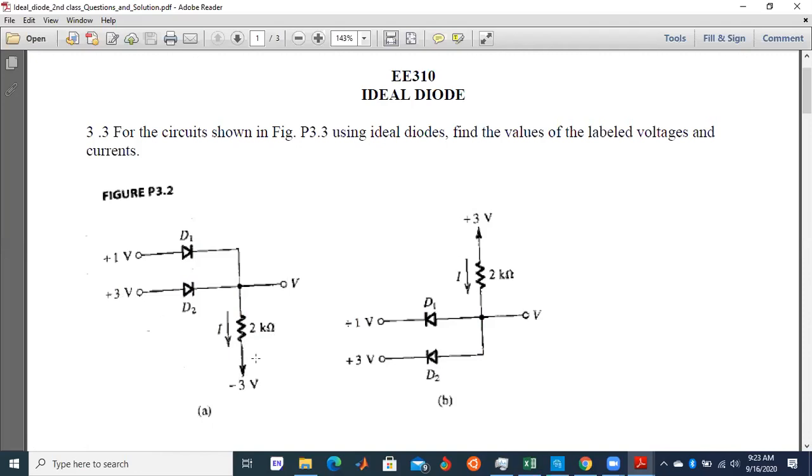Clear? Yes. Alhamdulillah. So the same thing is applicable to this one. If you want to solve this one, you have to be very, very careful about the direction of current. I can give you the same question like this, and I will reverse the direction of current. If I reverse the direction of current from here, now let's say the current is moving like this. It means that you will subtract this one from this one divided by this one.